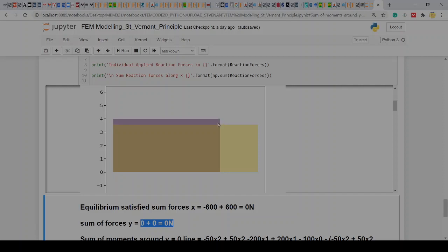If you for instance have a rectangular structure like this, and you start looking about two heights away, so this height, about two of these heights away from where you made the simplification, things should already start becoming quite a lot more accurate. There's not a fixed answer, because if there's some variation there, it will take some distance for that effect to dampen out.